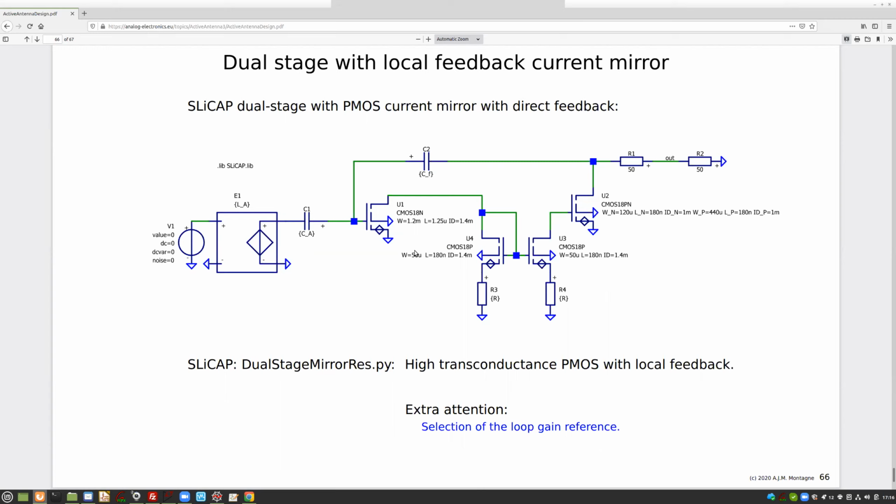But we still have a lot of options in increasing the current of the first stage to reduce the noise floor, because the crossover frequency for 1/f noise was still quite low. It was 31 kilohertz and it can be 100 kilohertz. There's still a lot of headroom for the noise design, I would say.